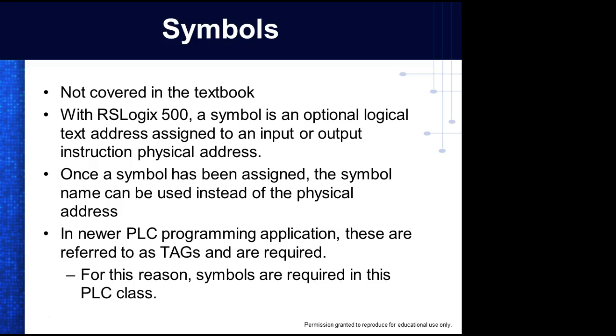So what I'm saying is every time you put in an instruction, you're going to assign it a symbol. And this will get you prepared when you move into RSLogix 5000 or one of the Siemens products. Those are all tag-based programming applications. Are we okay?